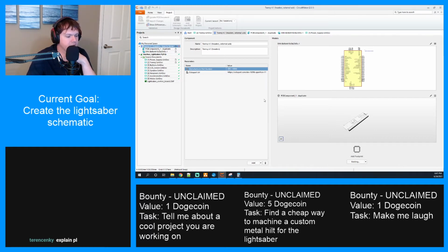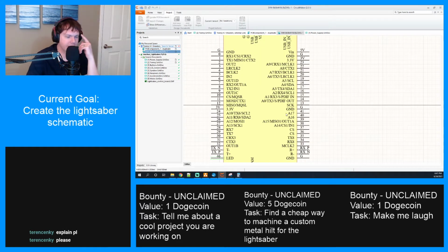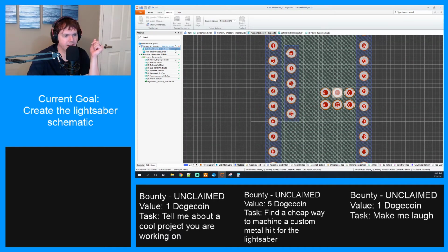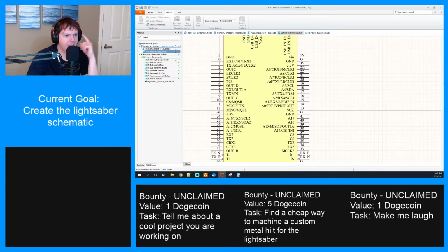Oh, yeah, if you just showed up, sorry. Basically, it's throwing an error because this device has multiple ground pins, and these numbers out here, what are known as the designators, are the things that match the pins up to the actual footprint.